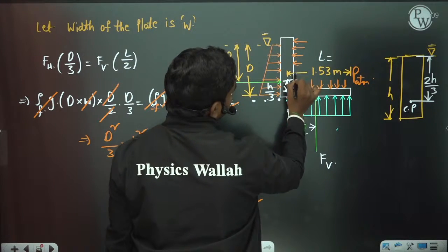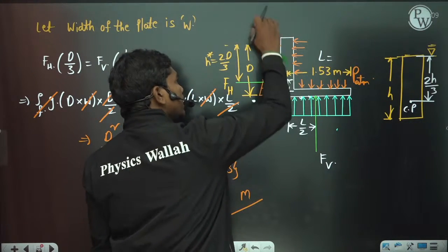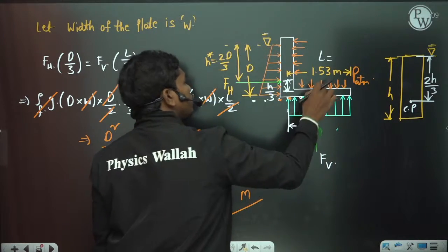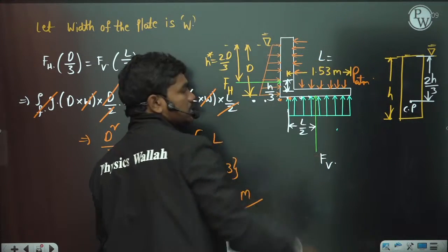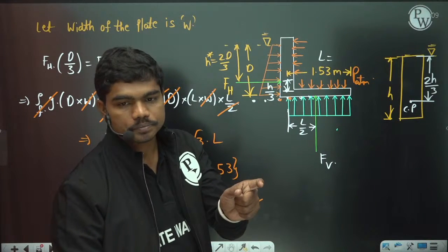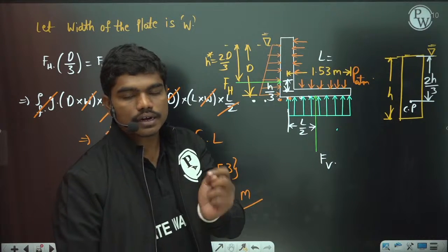So that's why the pressure at this point is just taken as P, this difference, because actually the pressure at this location is P naught, PATM plus rho g D. But since PATM is also in the opposite direction, the net effect is due to the pressure component rho g D. Okay. Yes, PATM will get balanced on both sides, of course. Clear?